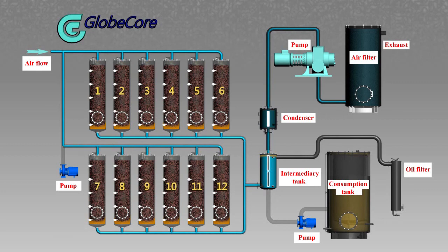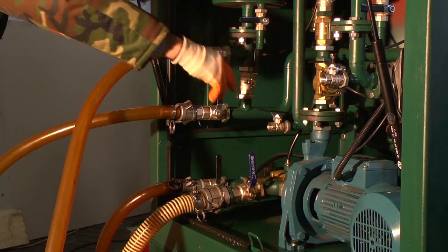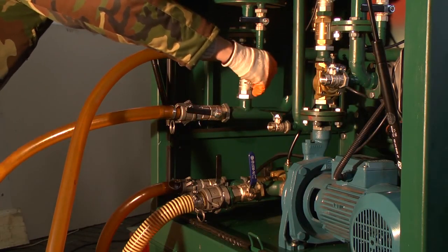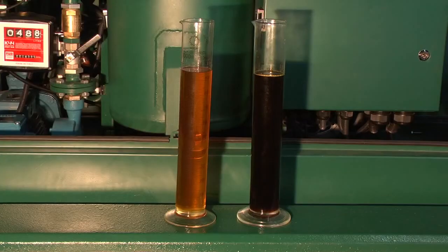Regeneration machines can be operated continuously. The only difference with a regular machine is an additional bank of sorbent columns. During operation, part of the columns regenerate oil, while the rest are in sorbent reactivation mode. After reactivation is complete, the machine is ready for operation again. The bypass line opens, and the regeneration system and the degasser continue to treat the oil in tandem.